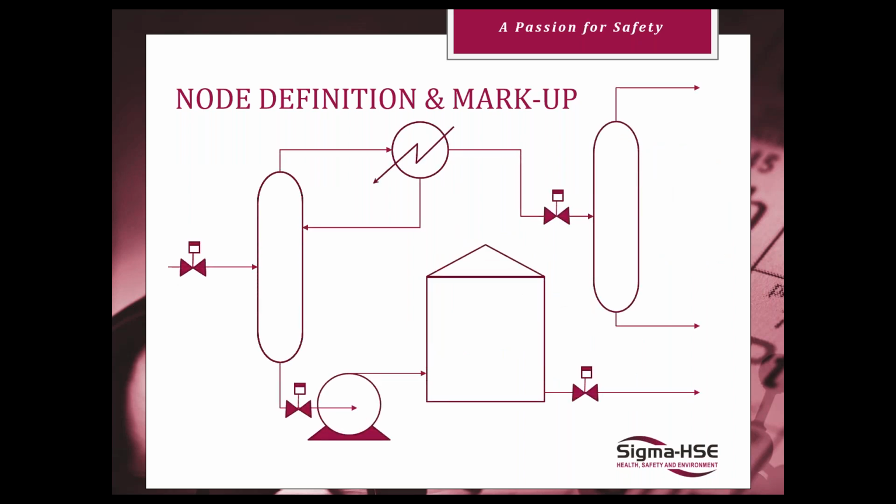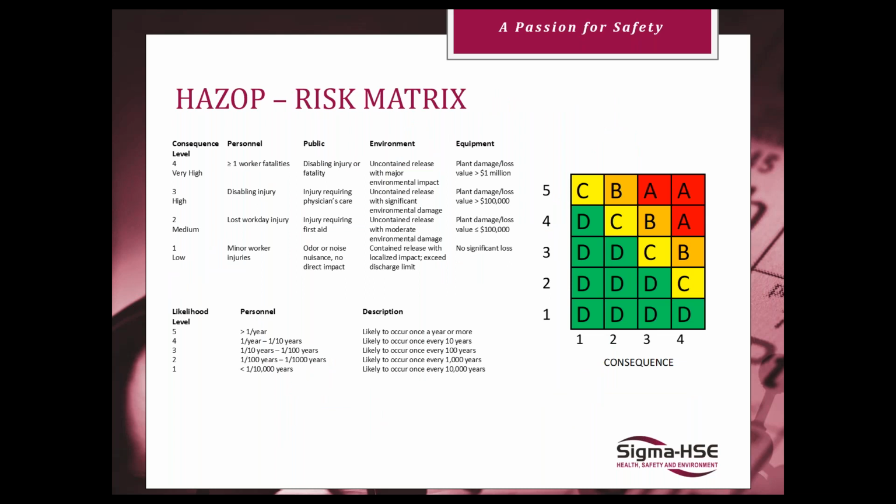So within each P&ID, it would be marked up. You would highlight, this is node 1, this is node 2, this is node 3, so everyone looking at it can see what is actually part of that node. From this green line to these green lines is one node, and then here to here is another node. So you're only paying attention to initiating events that fall within that node. Consequences may fall outside of the node, but your initiating event has to occur within that blocking.